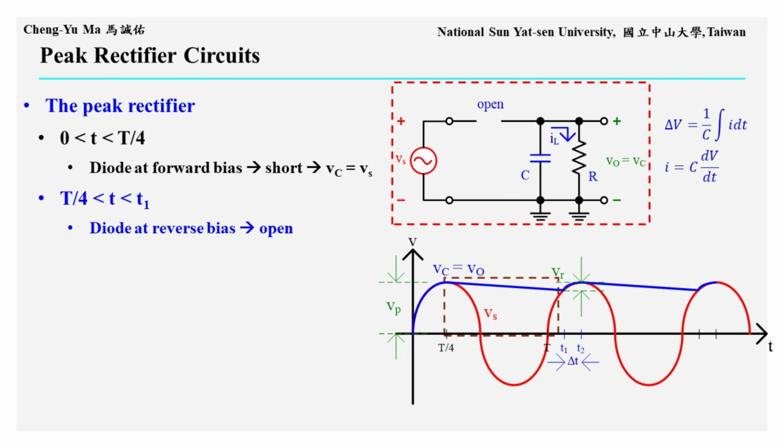Since the capacitor discharges through resistor R, this is an RC discharge process. The capacitor voltage follows the standard exponential discharge relation. The capacitor voltage Vc equals the initial voltage Vp multiplied by exponential of negative t prime over Rc. Here, t prime is the discharge time, and the entire ratio, negative t prime divided by Rc, is inside the exponential function. For a fixed discharge time, a larger Rc product leads to a smaller change in Vc.